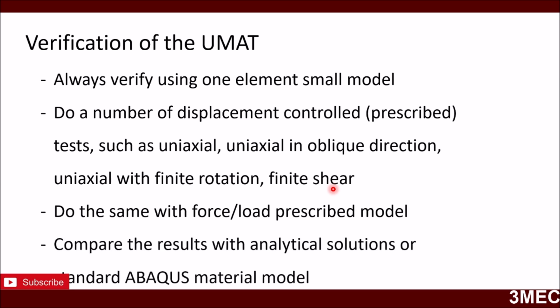If there are no default models available, then look for some analytical solutions for the theory which you have implemented in the UMAT and see if you can verify and validate your UMAT with those for different types of loading, because it is very important that your UMAT works for all sorts of cases and you have taken care of all the glitches and issues which you can come across in the UMAT. So I hope this makes sense, and you have now learned how to implement a simple linear elastic model in ABAQUS using a UMAT in a static analysis.